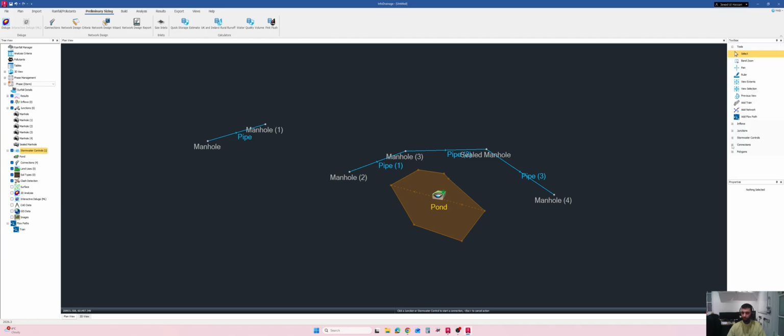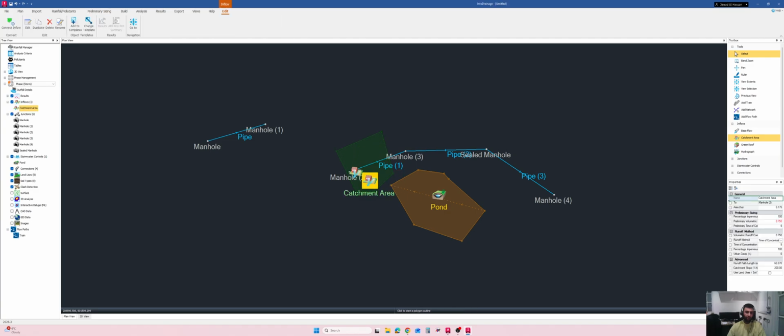For example, connections, you will have the inflows, and then you have the catchment areas that you can again select. So this is one manhole, this one will be our first, and then right click. Once you have the last point, you can just right click and it will automatically join and close the polygon. And then for this one you can have another polygon here, here, here, and then right click. And if you have another one, you can just draw back to back.